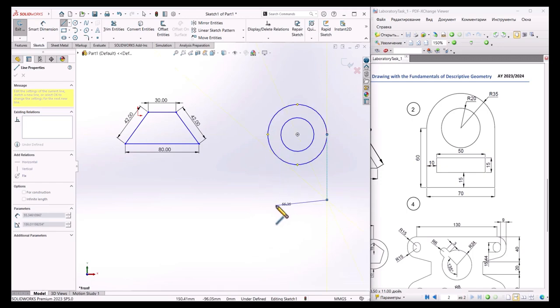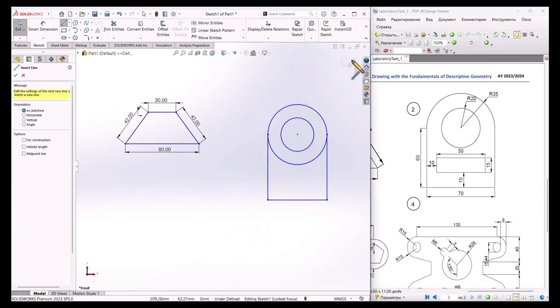So to connect as a tangent on that side also, just go there without clicking, just go with the cursor and then go like this carefully. So that dash means that is exactly an equal place, and then when you see the yellow minus, that means ideally horizontal, so click here. So now if you go up, that will be tangent also, so double click, disconnects.